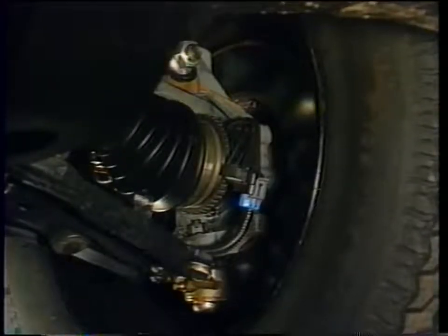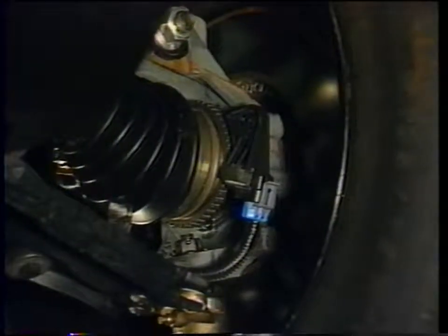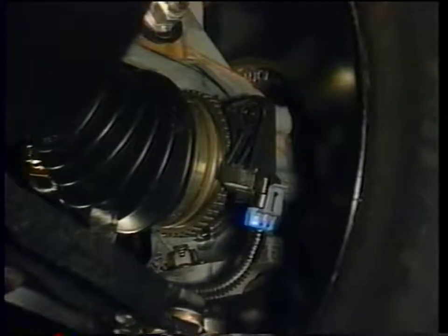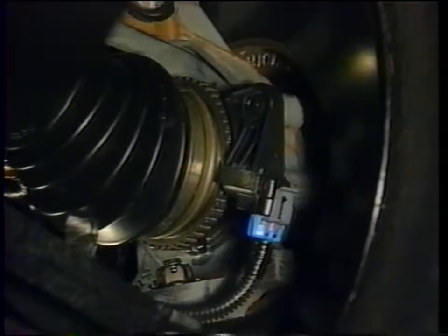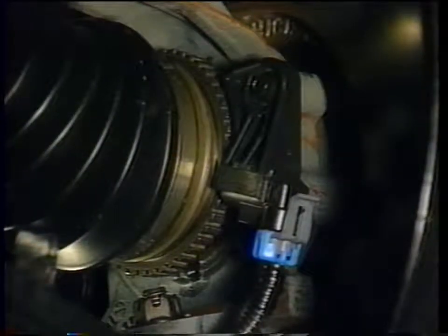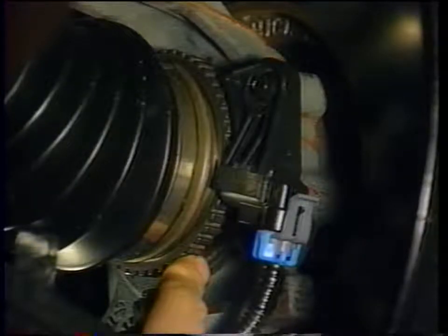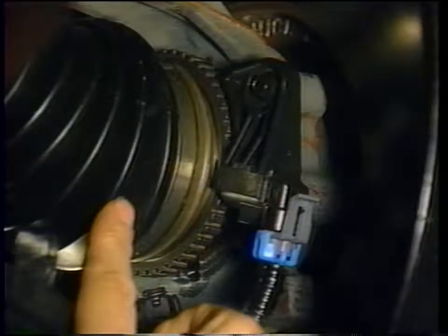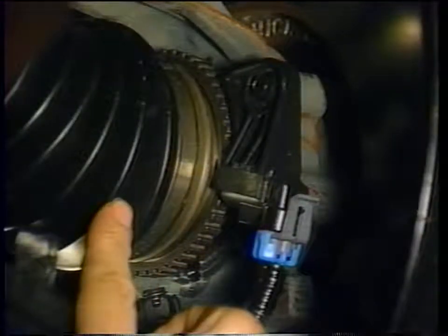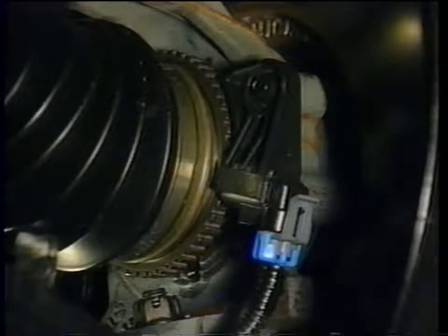Delco 6 ABS has 4 wheel speed sensors. The front ones are mounted on the steering knuckle assembly. The sensors are non-adjustable, so there's no air gap adjustment to make if a sensor has to be replaced. The sensor rings for the front wheel speed sensors are on the outside of the outboard constant velocity joints, which means the CV joint has to be replaced if the sensor ring has been damaged. You must also make certain the outboard CV joint has the correct sensor ring for the application you're replacing.